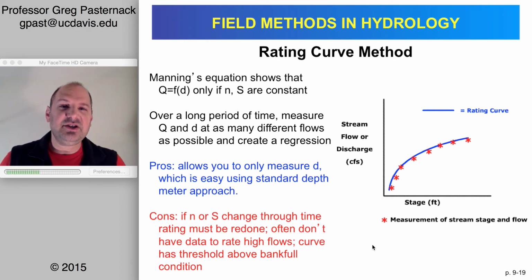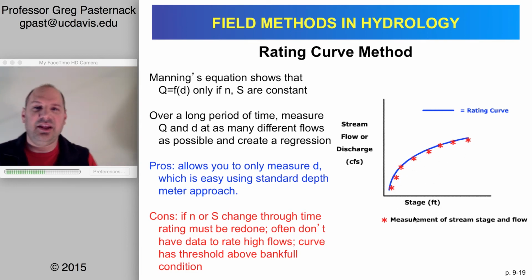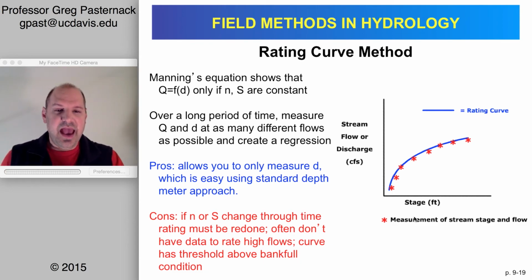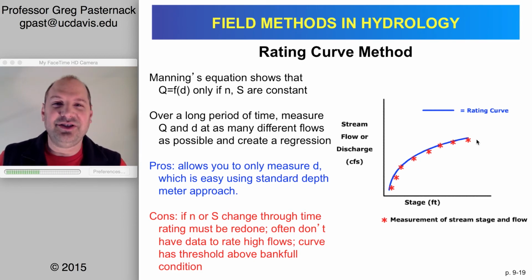Because of this, discharge measurement is expensive. You have to have, again, full-time hydrographers going out to all the places you want to know discharge, measuring each site 30 times or more a year. And not just at low flows that are easy, but you've got to get out there in the floods. And Murphy's Law of Hydrology says floods happen at night. So then what do you do? You're going to get out there in the middle of the night.